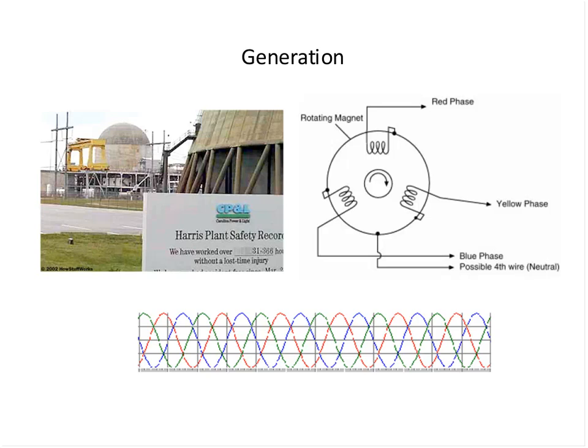So we found an optimal way that provides as continuous a power as possible without being too cumbersome or expensive by putting too many coils. That's why the sweet spot was 3. So just keep that in mind. Why isn't it 4-phase or 2-phase? So with this 120-degree out-of-phase, 3 sources are now being carried on the transmission line.